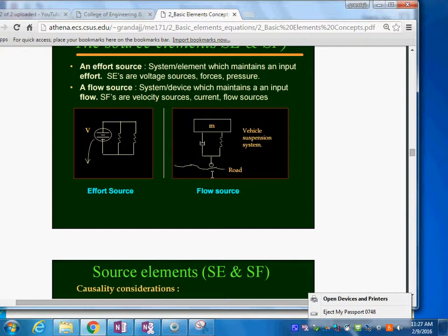So in fact, when you go on the road, it is providing a velocity input. But you could argue, I feel the force. Yes, this is true. But the force is a reaction to the input. See, that's the difference. There's no force input, but there is a velocity input. So if you enter something with a velocity, it has to go through the dynamics of the system to get a response. So there are those two possibilities.